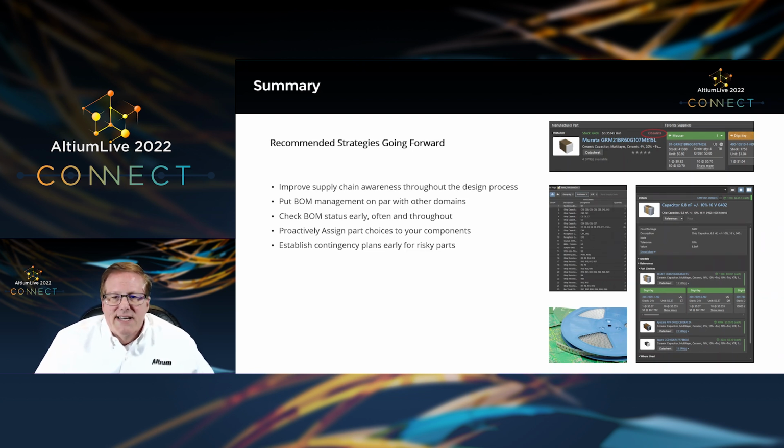In the past, when I would submit a board and that part wasn't available, I heard from the manufacturer. I had to jump through all kinds of hoops. This way, we've already pre-positioned known good substitutes that they can use so that you can get your boards back working properly. Again, establish contingency plans early for what I call risky parts, and parts that you really, really need that may be difficult to get in some cases.